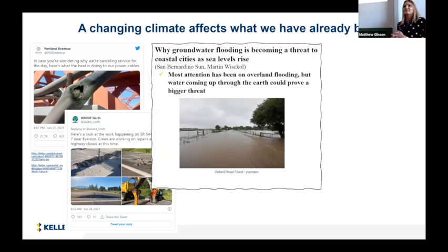We have sea level rise. And at Keller, we're doing a lot of work for coastal resiliency to address sea level rise. We do a lot in New York City, around Manhattan. We also do it in Florida. But an interesting part of sea level rise is the associated groundwater level rise, causing overland erosion and things like slope instability. Also, for our buried infrastructure, you can think pipelines and tanks that we've already put in the ground, if the groundwater level rises, that can cause serious damage.